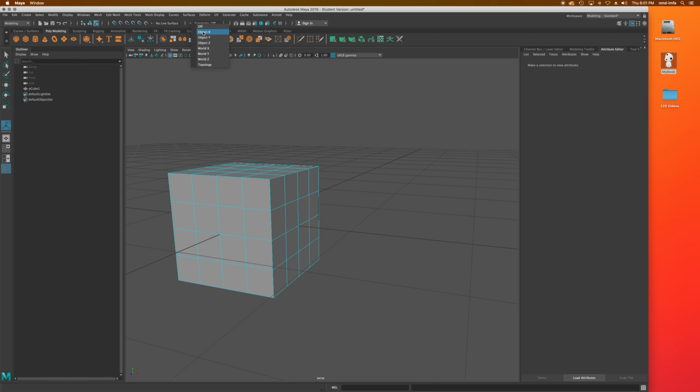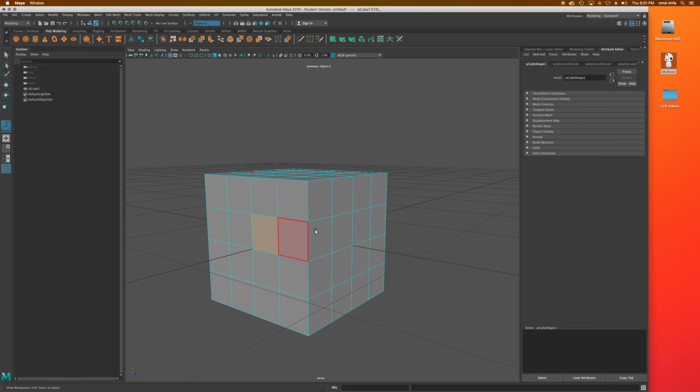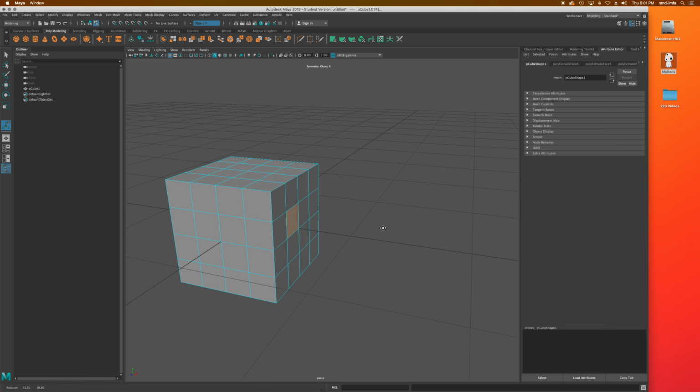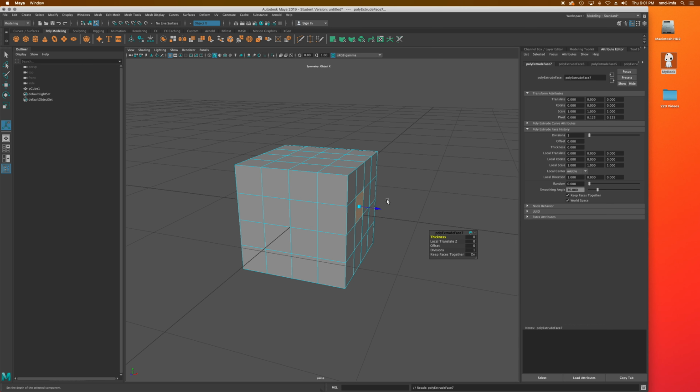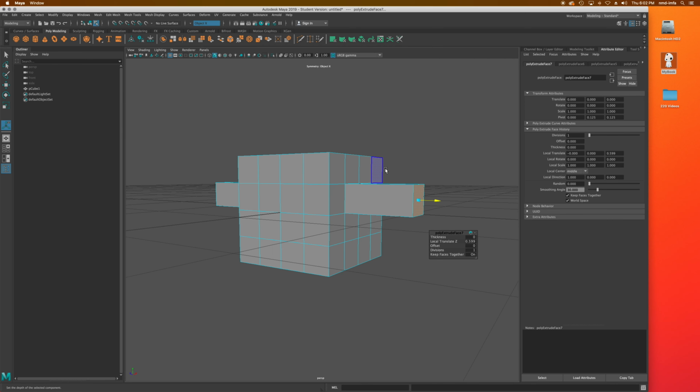So X-based symmetry. So if I click on that, you'll notice it made a selection on the other side, almost like I had turned off that camera-based selection, right? Well, watch this. As I extrude now, it's going to extrude out of both sides at the same time. So if you're working on a symmetrical object, this is really, really powerful. A lot of people do this as they're working with character modeling. I'm tilting that, and that symmetry is all working on that X-plane together.